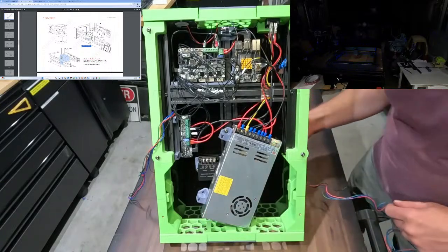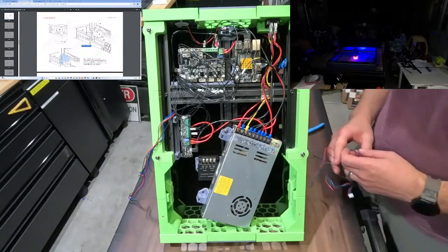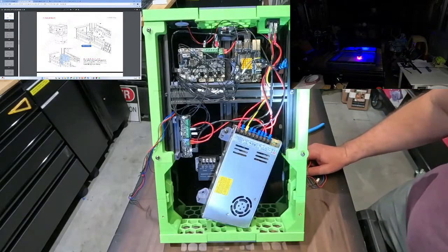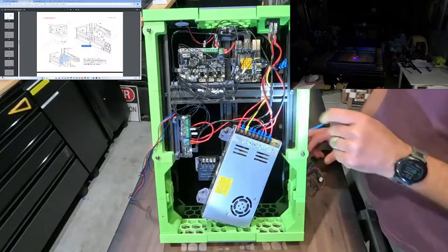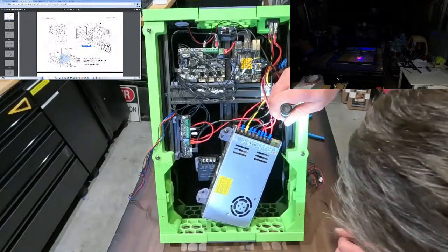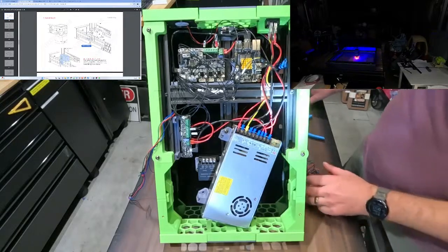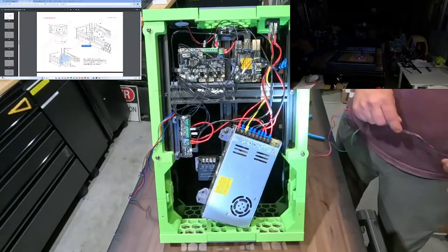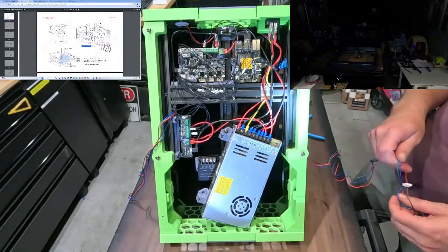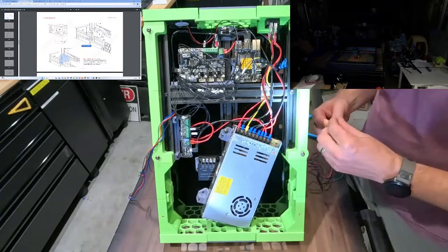And as you can see, the access port for the cable for the motor is literally right where my finger's blocking, so you can see it. So we'll get another light. And it's right there. And so I'll grab a handy dandy pointer. It's literally right here. It's this little tiny square. And that square is underneath the power supply. So when you guys are doing your builds, make sure you route and run your X and Z motors and the cabling for the X and Z motors prior to getting all mounted up.